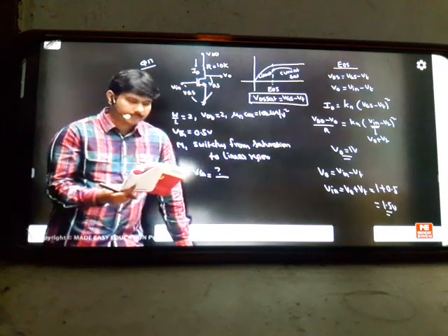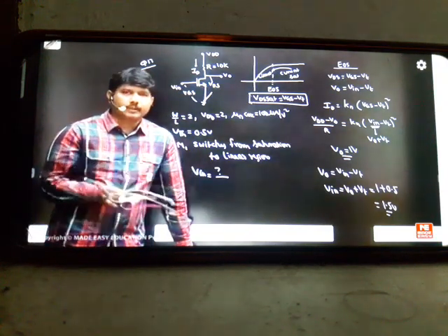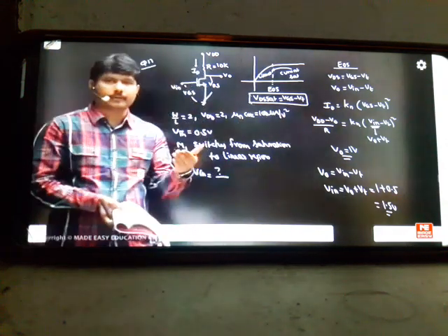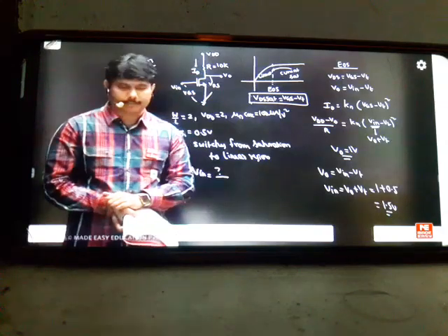Two more questions of this type they'll ask you. So whenever they say the words switching from saturation to linear region, it is called a boundary question. For a boundary question, you can take the help of this equation to solve the concept. First I found V0 by the quadratic method. From that I found the input relation from that equation. So this is the story.